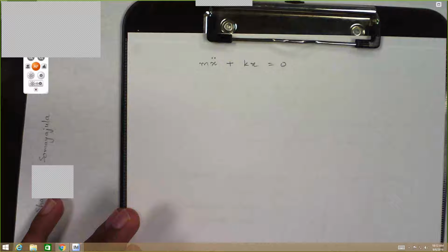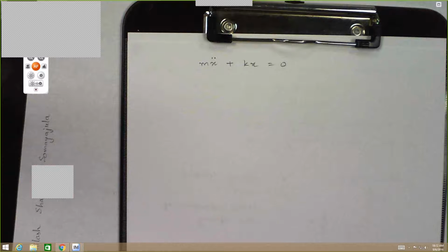So it gives you an idea that you would always want to construct an equation of motion considering the origin point at the static equilibrium. And that does make sense because when you're considering dynamic forces, we are considering an oscillation about the static position. So it makes sense for the static position to be taken as the origin point in deriving your equations of motion.